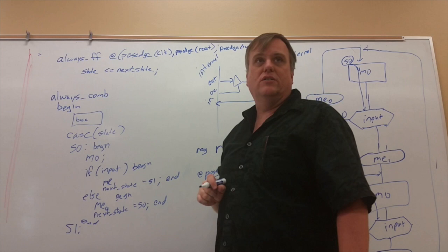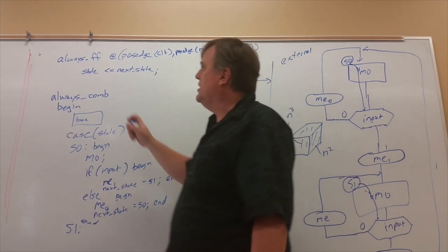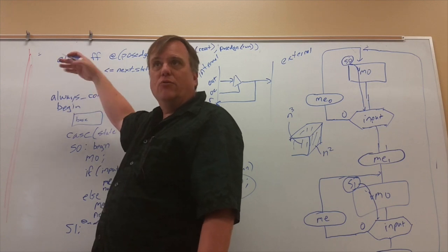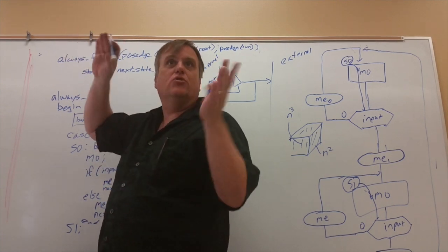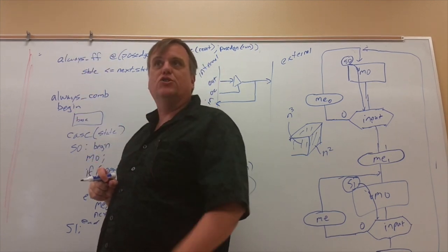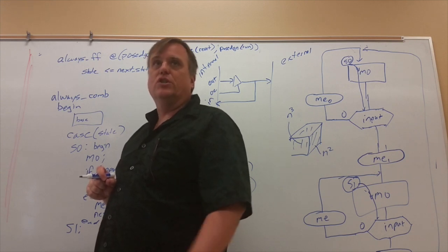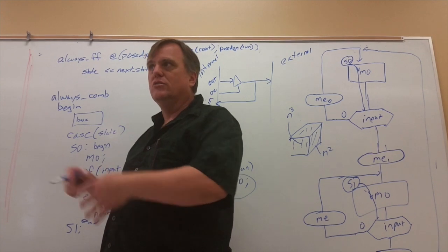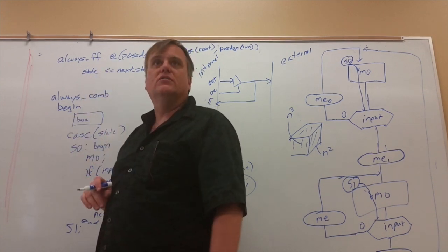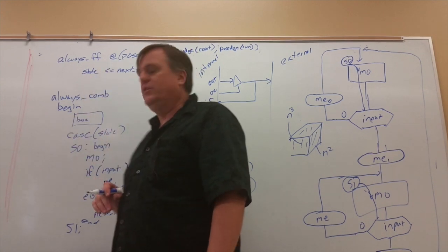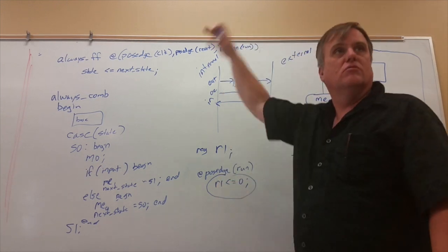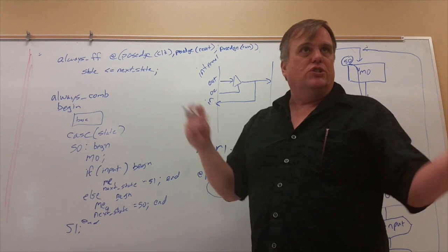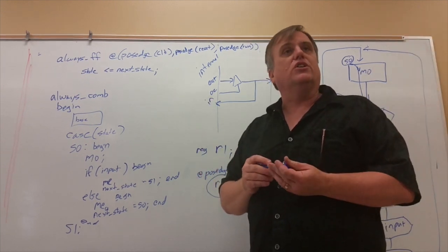I could put all of them in, and I could check to see if I'm at my run state, or if my last state was 0. So I could look, was it a posedge of run? Was it a posedge of reset next? Was it a posedge of the clock? And just handle each one, and then do this assignment inside the flip-flop, which I could then do by the asynchronous clear, and it becomes a clear.